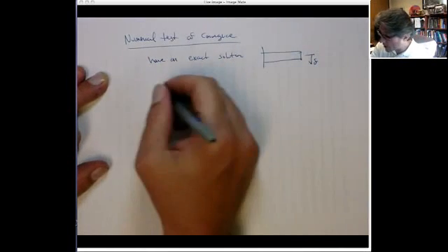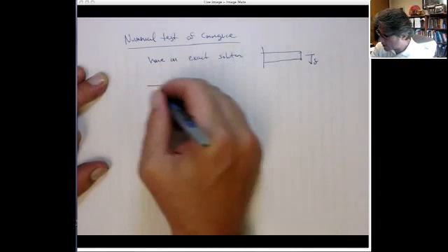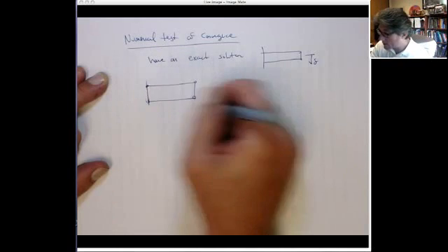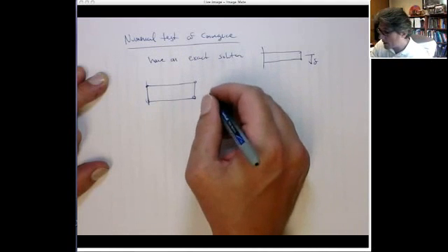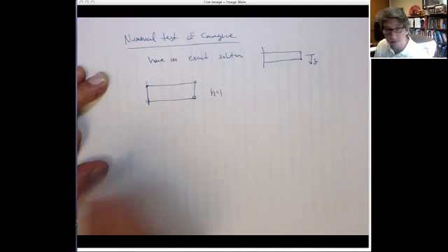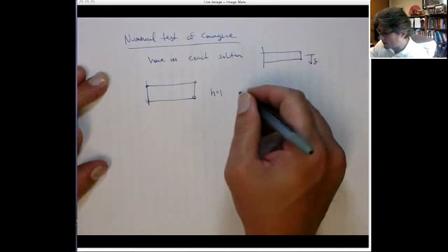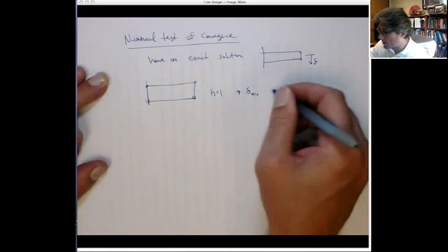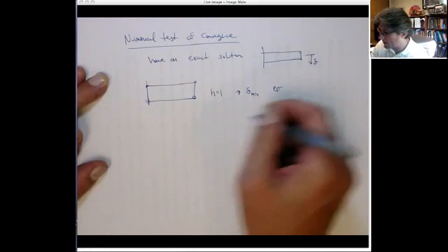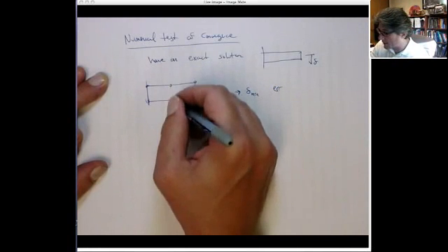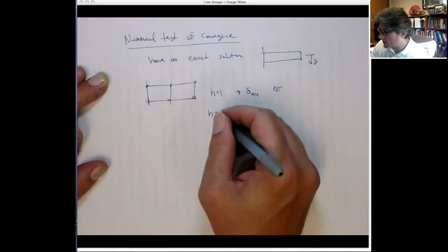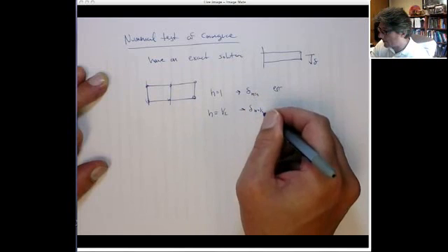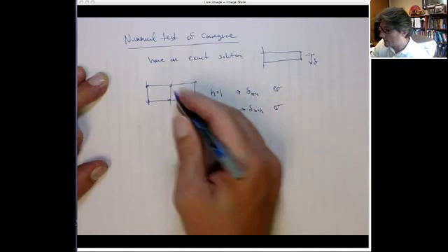So then I can start off with one element, this would be, let's say, about h equal to 1. And then we can get the delta for h equal to 1, and then we can compute that error, okay? And then we can take the mesh and refine it. That would be h equal to 1/2. And then we can get the delta at h equal to 1/2, and then the error, and so on and so forth.